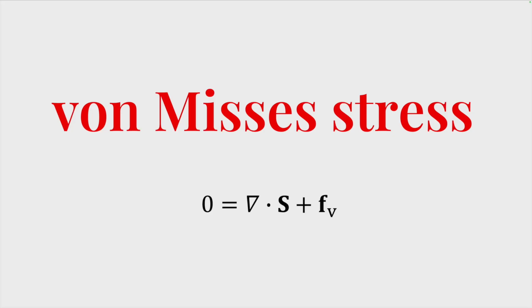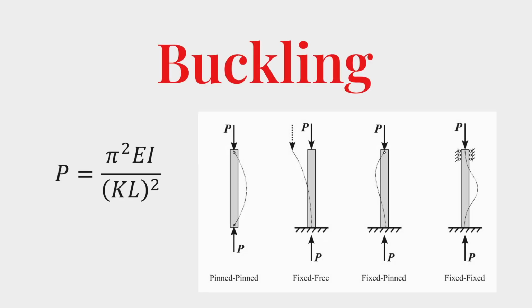Heel failure is determined by von Mises stress. This is the value of stress that an object can withstand before it yields, or in this case, fails. Physically, this would mean that the heel would have broken under a certain amount of force. The buckling study predicts the load at which a structure becomes unstable and collapses suddenly, even if the material has not yet reached its yield strength.